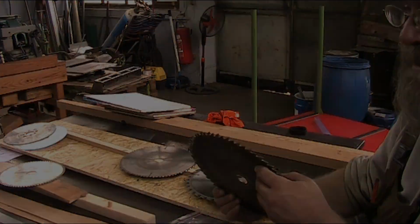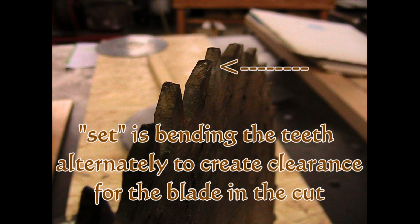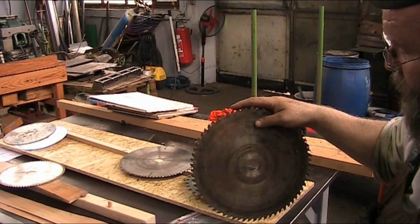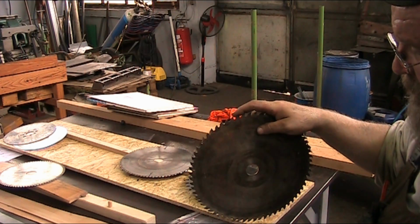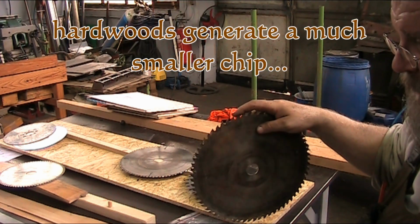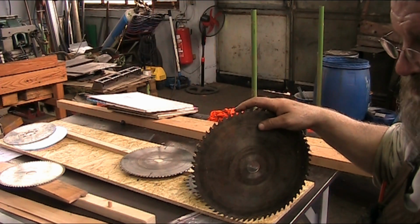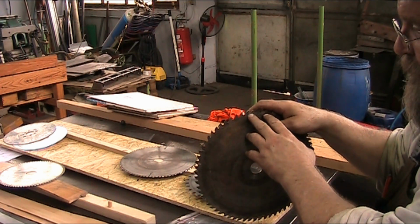These teeth have set in them, so with this saw blade we have a 15 millimeter spacing, which means this is more suitable for material that is harder to cut and generates a smaller chip during its travel through the material.